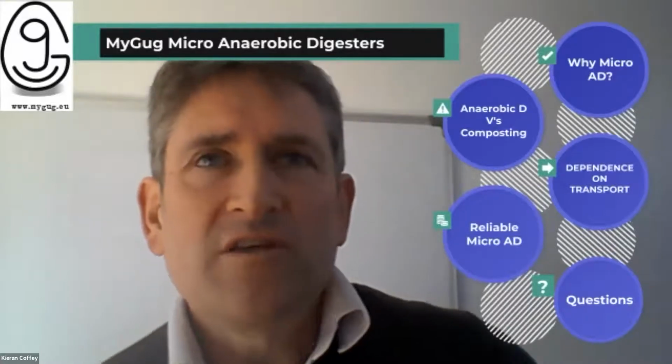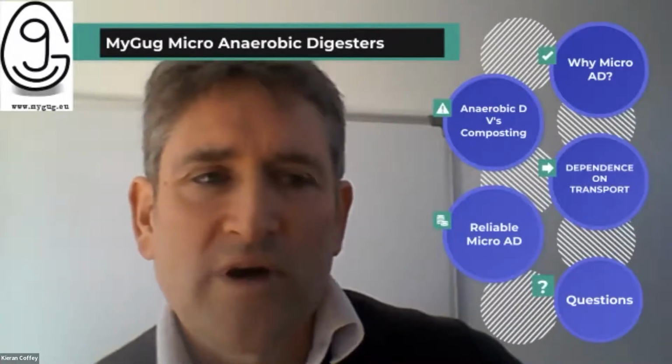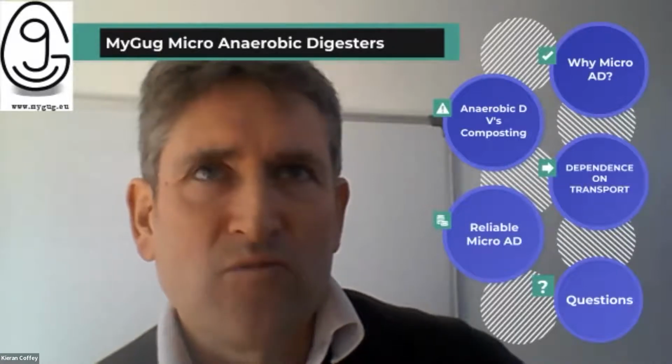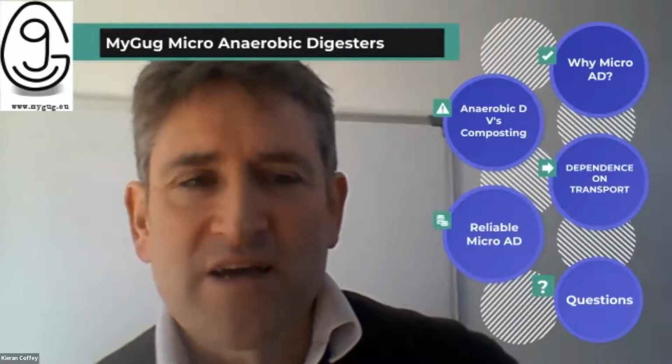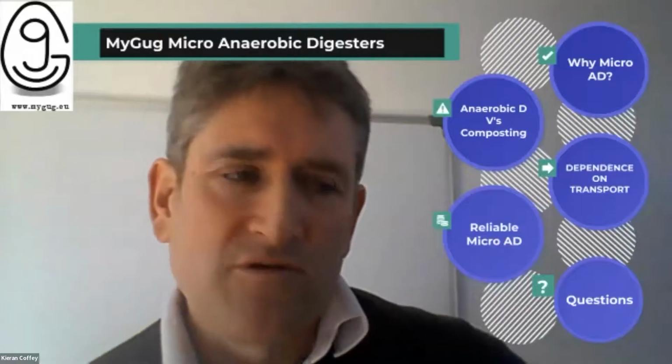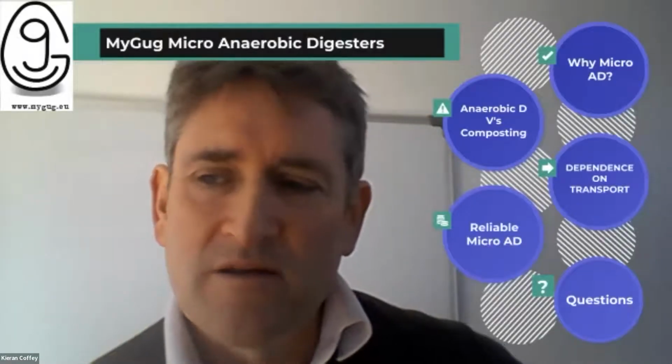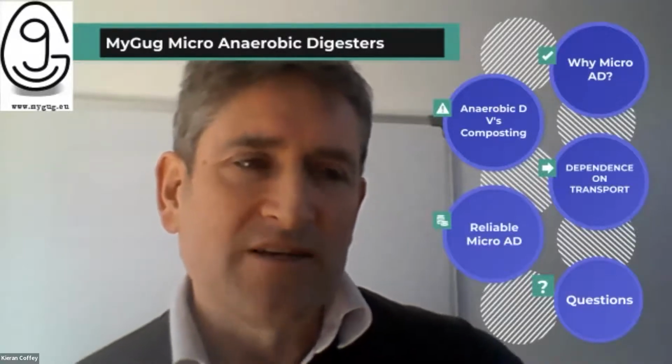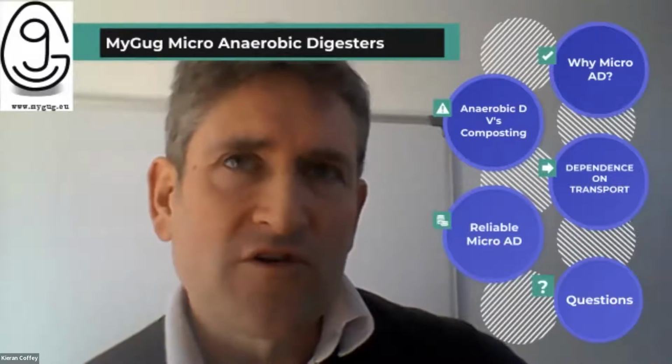Question here on the bacteria culture. Do you need to add bacteria culture before adding your food waste to seed the unit? Yes, you seed the unit. Once you seed the unit, it should work away. Sometimes if you have too much of one particular type of food waste, you might have to add micronutrients or some bacteria very occasionally. To seed the unit, what would you use? Would you just start adding the food waste and over time the bacteria start to activate? No, you seed it with a sludge, or there's a company in Dublin we work with where you can get dried bacteria, and you just mix that with warm water and you start.